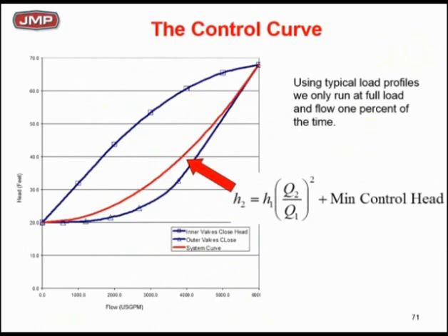But here's a message again. Let's assume I need 3,000 GPM. What pump head do I need? What pump speed do I need? If the two-way valves closest to the pump are open, then I need about 25 feet.